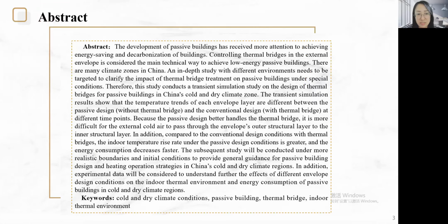The transient simulation results show that the temperature trends of each envelope layer are different between the passive design and the conventional design at different time points. Because the passive design better handles the thermal bridge, it is more difficult for the external cold air to pass through the envelope's outer structure layer to the inner structure layer. In addition, compared to the conventional design conditions with thermal bridges, the indoor temperature rise rate under the passive design conditions is greater, and the energy consumption decreases faster.